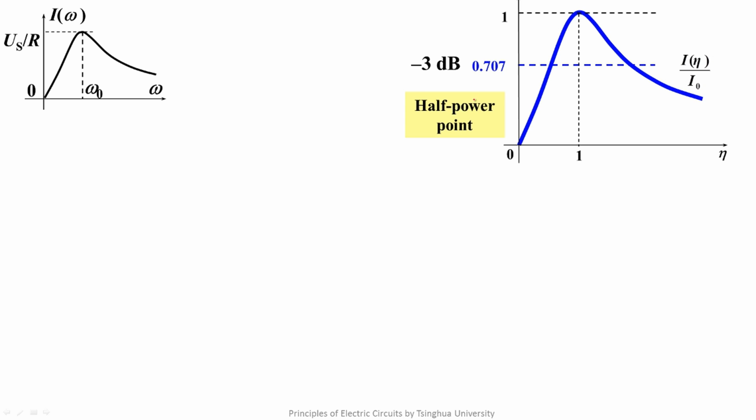We are interested in the fact that the magnitude frequency characteristic can be regarded as a bandpass filter. It has two intersections with 0.707. Signals within the frequency between the 2 points can pass, and signals with other frequencies are all attenuated. So we should solve the value eta of the 2 points. They are defined as eta 1 and eta 2 respectively.